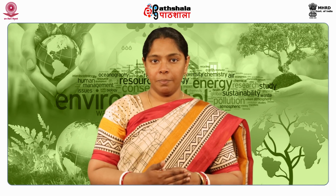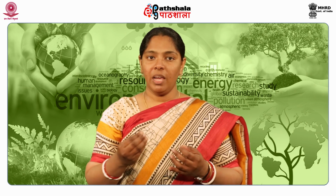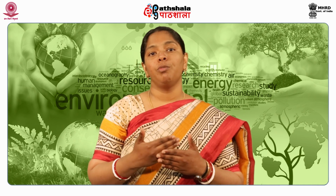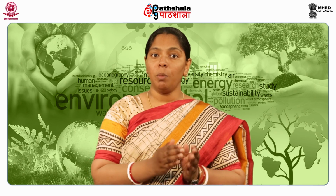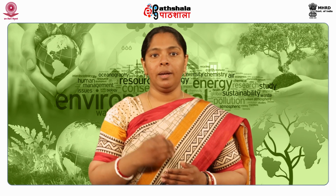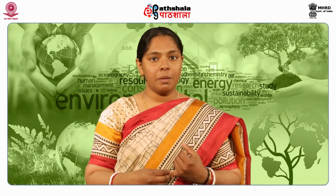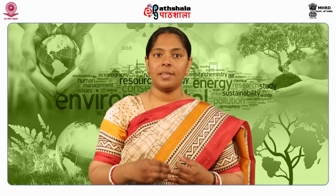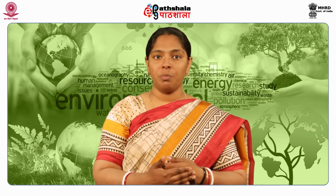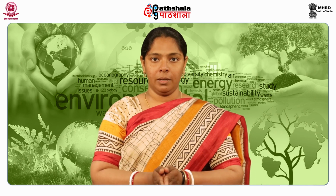So, to summarize, we have seen what is biogas digestion and what is biogas. We have seen a brief history of the biogas and what are the feedstocks which can be used for the biogas production. And we have seen the composition of biogas with methane as the combustible component in it. We have seen the biochemistry and microbiology of biogas production involving the 4 steps: hydrolysis, acidogenesis, acetogenesis, and methanogenesis. We have seen different types of biogas plants and different components of a biogas plant. We have seen the fixed dome, floating drum, and balloon type biogas plants.